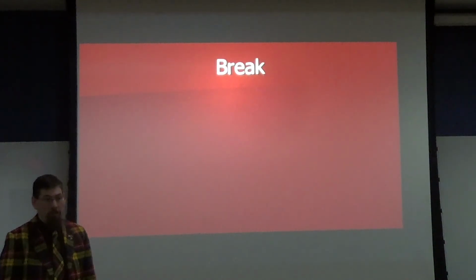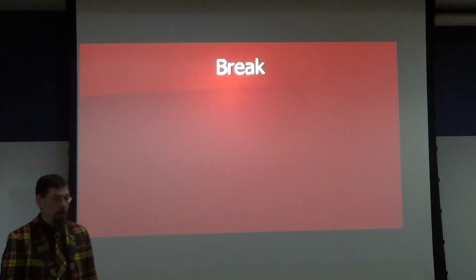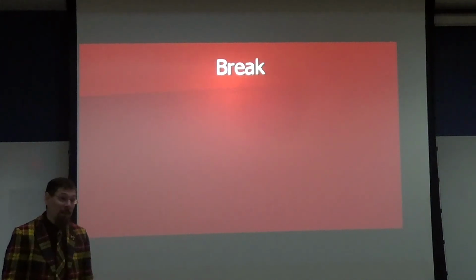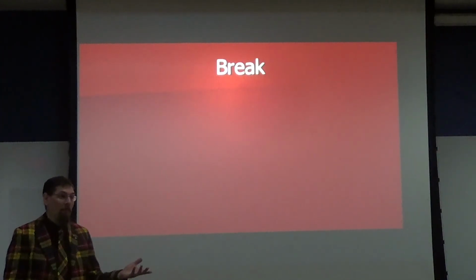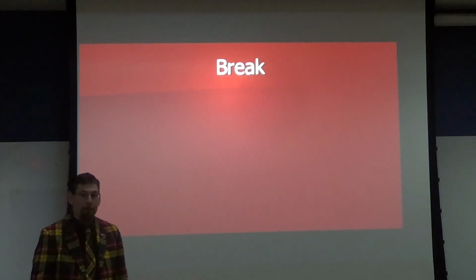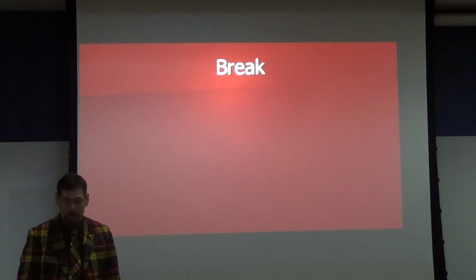I don't know what the typical output of the casting process would be, but you're going to definitely see them being equiaxed, and you're going to see in a casting properties that are basically the same no matter how you orient your test. So that's the main difference between a forging and a casting, besides, let's say, there's no porosity in the casting.